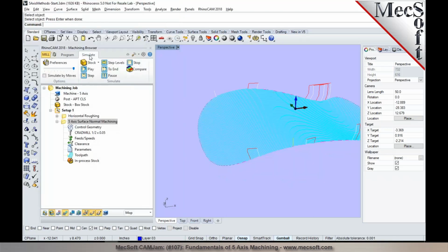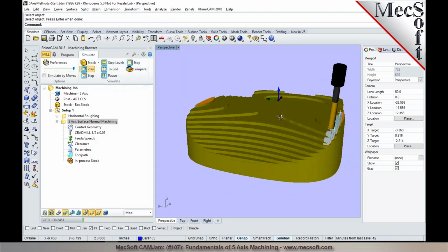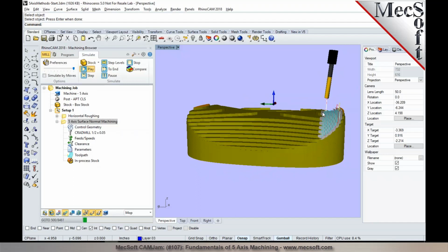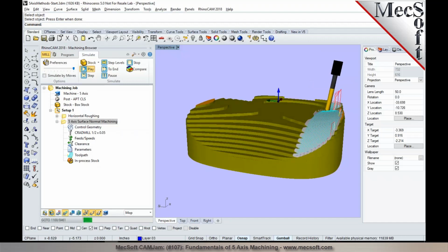So in this particular example, if I set a tilt angle in here, you will notice that the tool is tilting across, perpendicular to the direction of travel. These parameters for tool axis control are available in all of the 5-axis operation types. I'm just going to go over this in one of these operations, and it would work similarly in the other operation types as well.